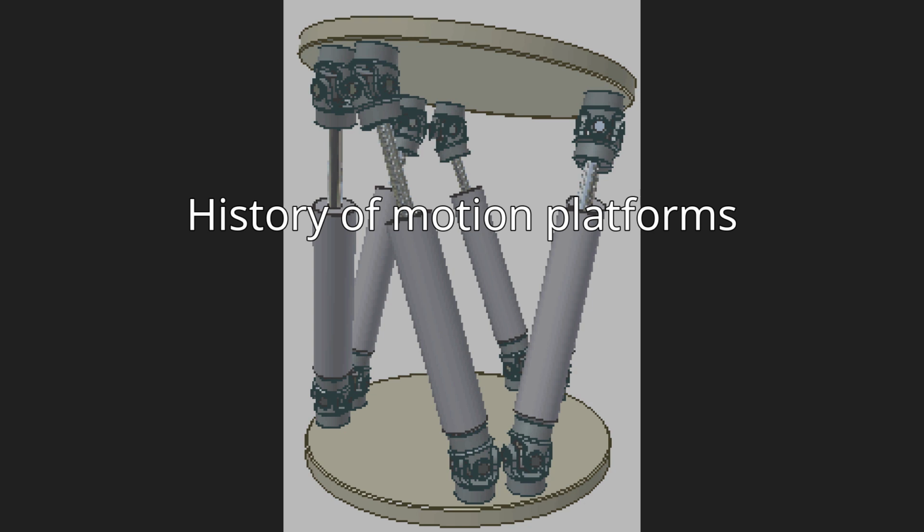Simulator motion platforms today use 6 jacks (hexapods), giving all 6 degrees of freedom: the 3 rotations: pitch, roll, and yaw, plus the 3 translational movements: heave up and down, sway sideways, and surge longitudinal. 6 DOF motions are powerful cues when combined with outside world (OTW) imagery. Motion platforms together with OTW imagery are used in flight simulation, driving simulation, amusement rides, and small home-based simulators.